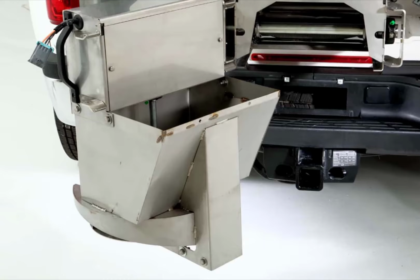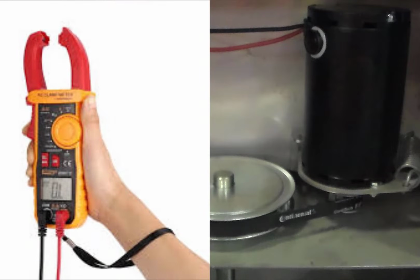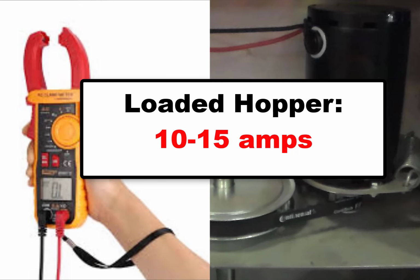Check for any jammed material in the chute that could be causing the spinner to bind. Check the bearings to make sure they are properly greased and not seized. With the unit plugged back in, use an amp clamp to check the amp draw on the motor power wire. With the hopper empty, the spinner motor should draw between 5 to 10 amps, and with the hopper loaded, the spinner motor should draw between 10 to 15 amps.